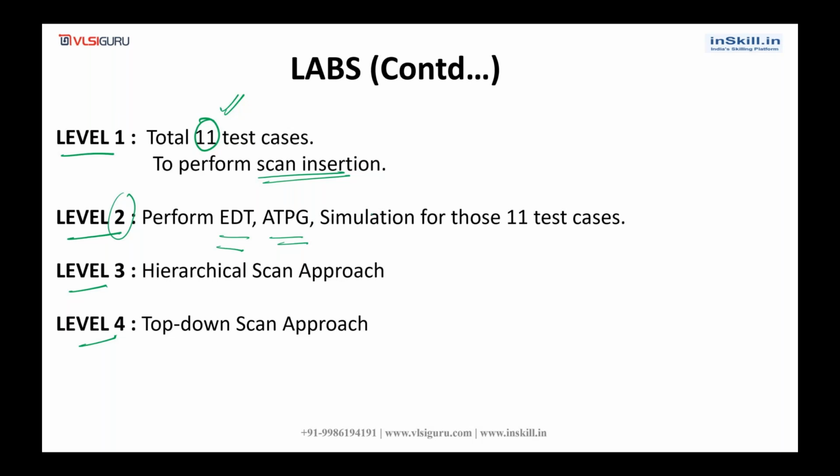For all those 11 test cases, we will be performing it. These are small test cases, with a maximum of around 100 flops. Level 3 and level 4 projects are more complex designs. Complexity is high. In level 3 projects, we will be discussing the hierarchical scan approach.